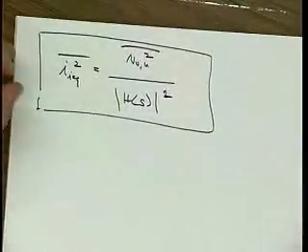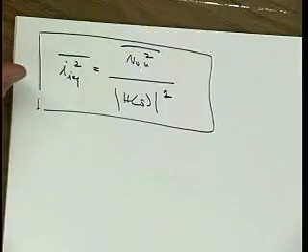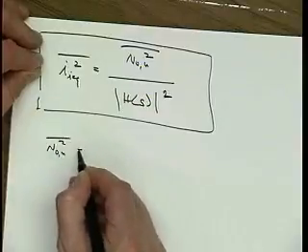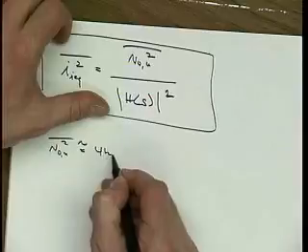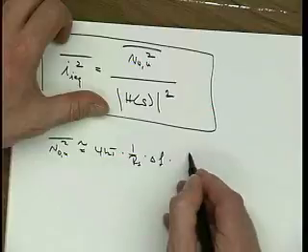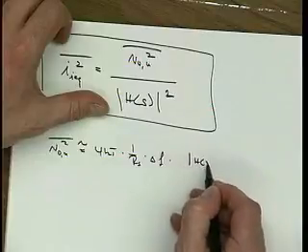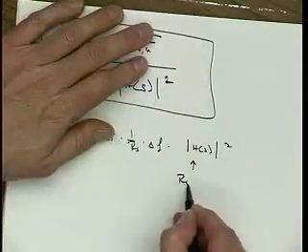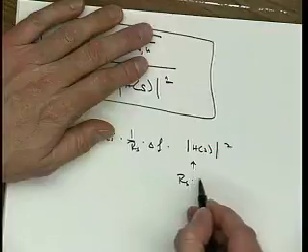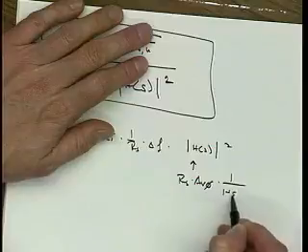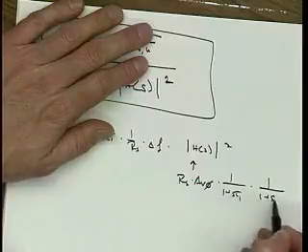Okay, so the noise in our example, V_on squared, was approximately equal to 4kT times 1 over Rs times delta F times H of S squared, and this H of S was Rs times A_V0, g_m R_L, times 1 over 1 plus S tau 1, times 1 over 1 plus S tau 2.